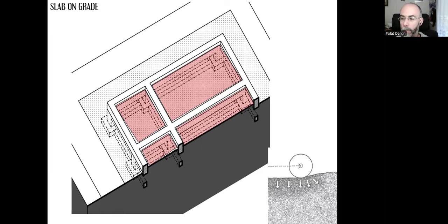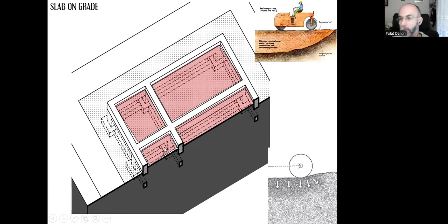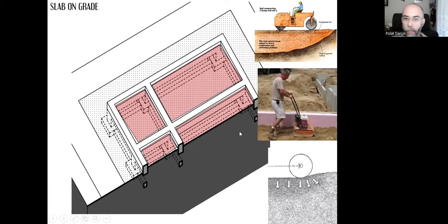Otherwise, as we apply more loads, as we apply building products, and as we put the people in, that means the load will be increased. The grains will be compressed at that time, and that can be dangerous. So we first compress it with certain heavy devices. These can be machines like that or objects like this, something like that.